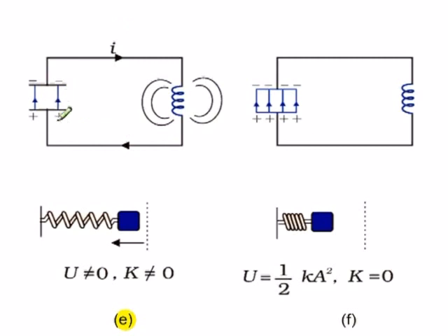Now the lower plate is positively charged and the upper plate is negatively charged, and hence there is some charge Q that is stored in the capacitor, and there is some current that is being drained out of L. So the electrical energy at the capacitor is not equal to 0, and the magnetic energy at the inductor is also not equal to 0, but it is less than UB max, and here U at the capacitor is greater than 0, still it is less than U max.